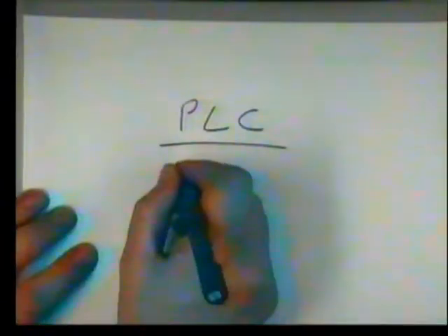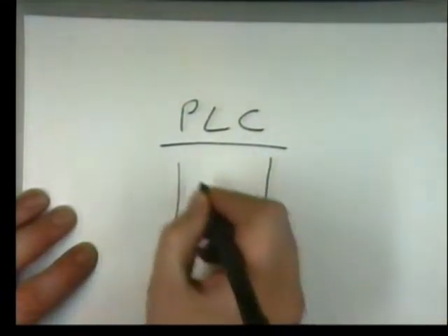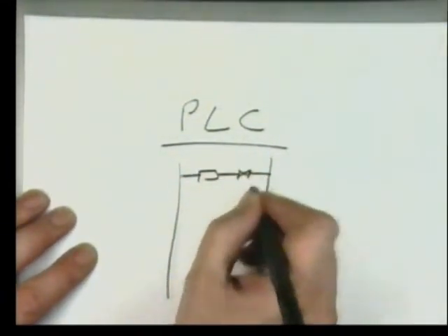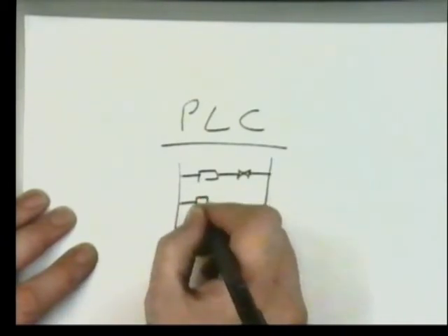The whole thing is compiled into a machine code that mimics the operation of the old-fashioned factory controller, and that is a PLC. So there's a very wide market for them because there is years and years of investment and knowledge in this ancient ladder logic technology. And a PLC, a programmable logic controller, is a unit that actually compiles programs that literally look like that. You draw pictures like this with relays.